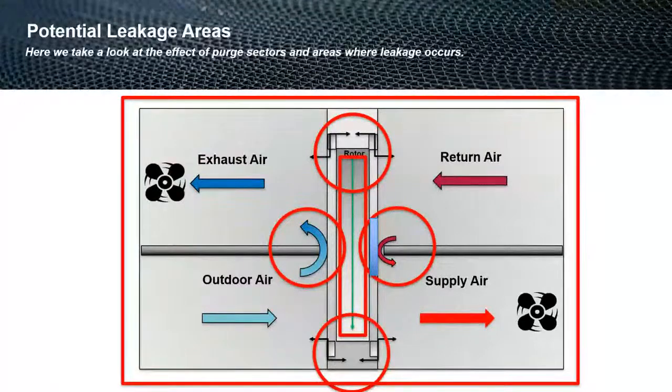So there's positive and negative leakage that's possible from the casing of the AHU. And I know within the Eurovent guidance that they've been doing a lot of work over the last 5 or 10 years at least to try to improve that leakage standard, with different leakage levels that are permissible. So when we start to look at the units as a whole, we have to consider every single component, the space where they're in, and everything else that goes with that as well.